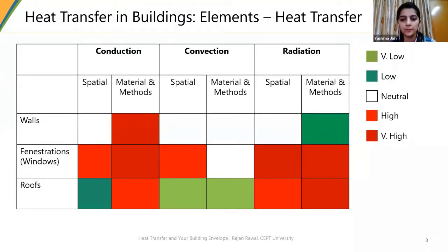Right. Next question: if we keep insulating material inside, does it affect the maintenance of the building material which is exposed? So be it inside or outside, how does maintenance factor in here? Most of the insulation material needs to be protected with an additional layer. Although there are some materials available, again, they cannot be used 100% exposed.